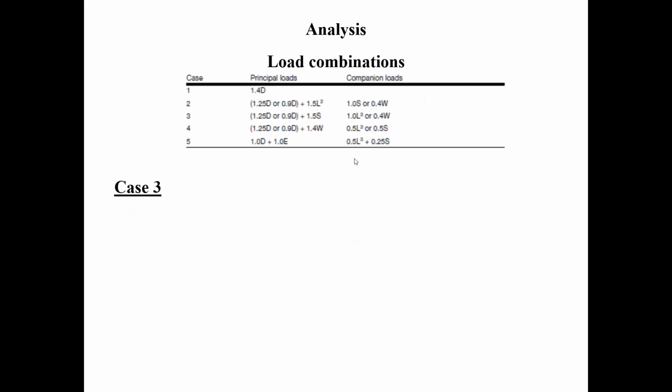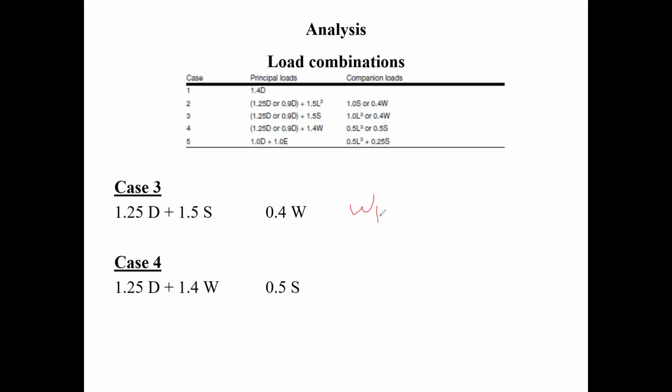Let's go here. So for case number 3, I have a WF equal to 0.94 kilonewtons per meter squared times what? It's going to be times our tributary area, right? No, I want to know what a WF is. A WF is not a tributary. It's a distributed load. Oh, sorry. Because the table gives me a WR value. I need to know compared to a WF value.